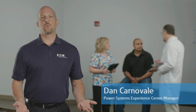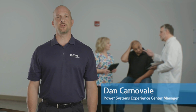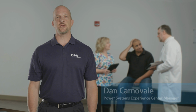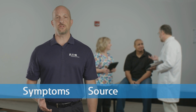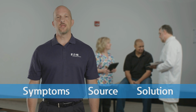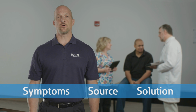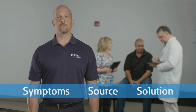Have you ever had a power quality problem and you felt like people were just suggesting solutions haphazardly, like a UPS or a surge protector, to see if they could work? It's very similar to the doctor analogy. You have to identify the symptoms of the problem before you can solve the problem. We say, identify the symptoms, determine the source of the issue, and recommend the right solution to correct the problem. This is the most expedient and cost-effective method to solving any power quality issue, and really any problem.